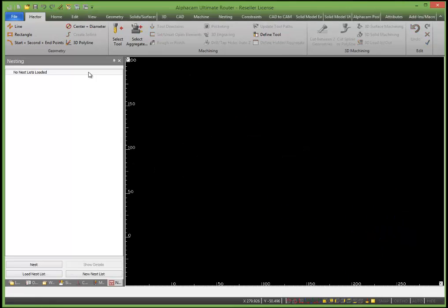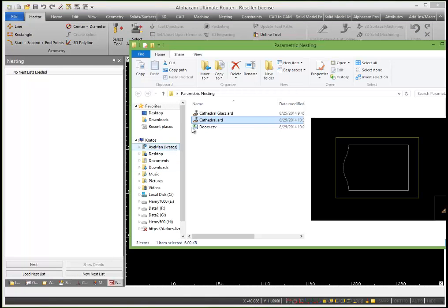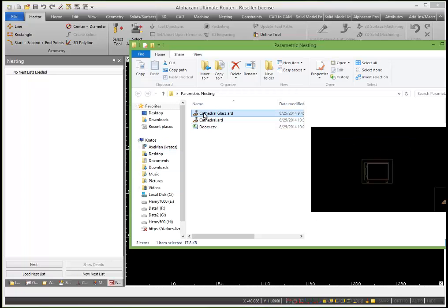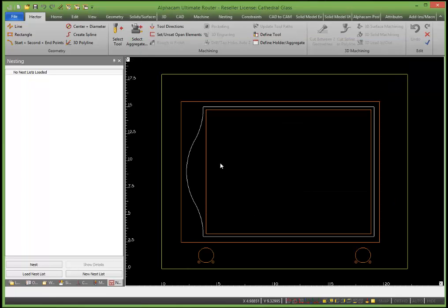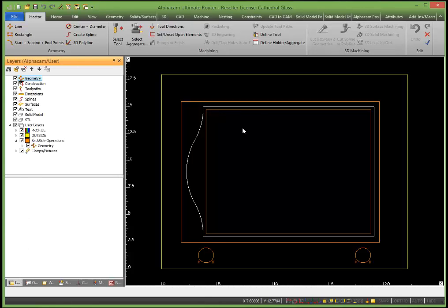This example, of course, is very well suited for MDF doors. So if we continue to talk about the example of the MDF door, we'll see that we also have a particular challenge, which is what we call backside operations. Backside operations are achievable by simply putting any operation that you want on the backside in a different layer. You can see here that I've got different machining assigned to different layers.